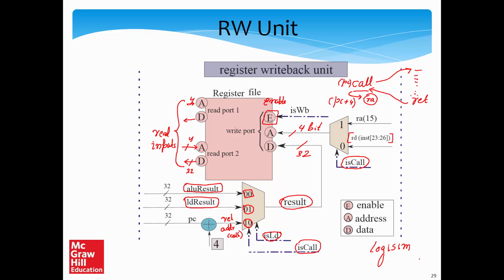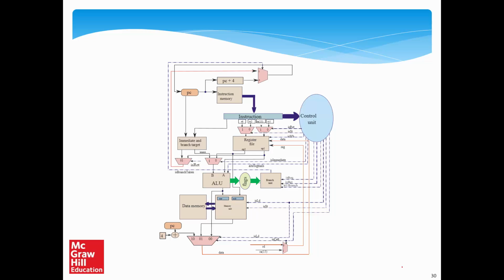So basically this circuit will work as is shown. Everything that is shown just has to be entered into Logisim, and Logisim has good support for drag and drop elements, so it is possible to design multiplexers and so on. That is one option, and those who know hardware description languages such as Verilog and VHDL can also implement it. You will find a Logisim model of this processor and a Verilog/VHDL model of this processor on the course website, and that can be a good starting point.